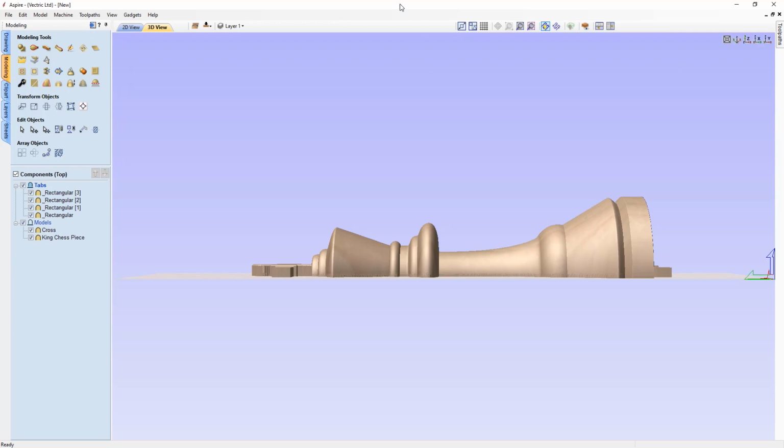What that will do is, as it comes down the side of our chess piece to the modeling plane, it won't go past that because there's nothing by it. It will stop there. We'll end up having a little cusp, and a little cusp almost looks like a little piece of a hand carving left behind. That will leave a seam all around the top and the bottom of our part that we're going to have to remove somehow in the finishing steps. But we can get rid of that, or at least help minimize it, by making the software go past that by using a limit plane.